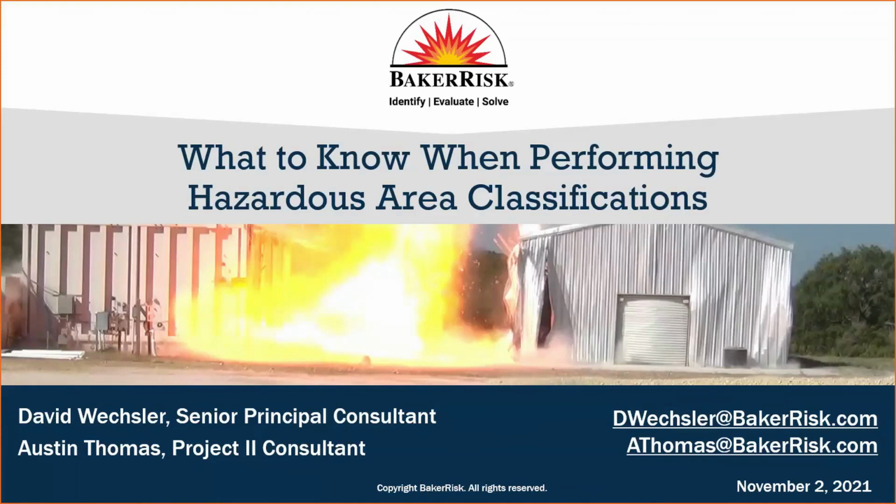How often should the hazardous area classification study be updated? There is criteria out there to address this. Some say annually, some say quarterly. My recommendation is that it is done every time you have a management of change process, that the management of change process should include an evaluation of what's going on in that area.